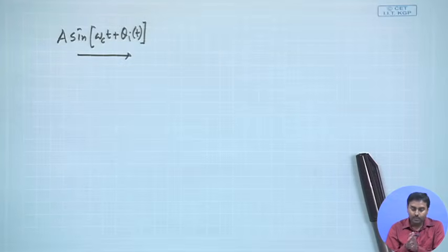You might be asking, where do I get this carrier? That is the first question, because the PLL we are designing will be at the receiver circuit, and I do not have the carrier. We have already talked about squaring and a narrow band pass filter; passing it through that, we get the carrier with whatever carrier phase and carrier frequency it has.